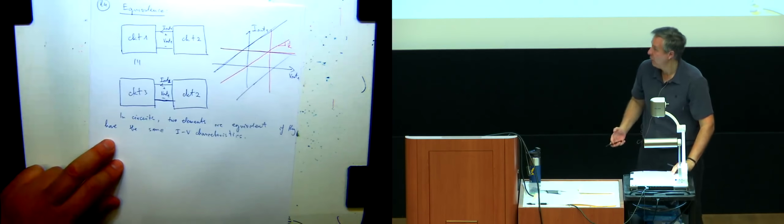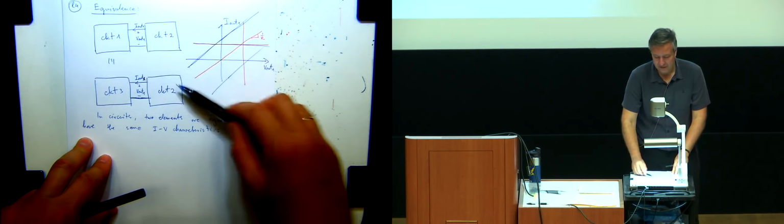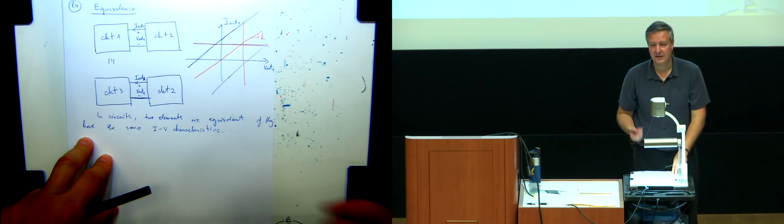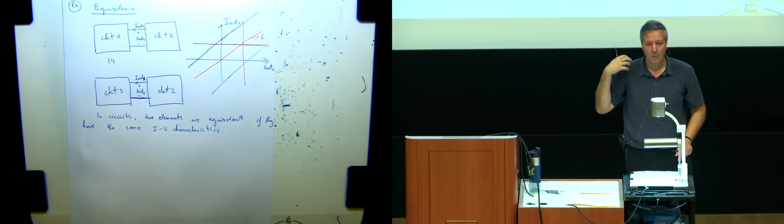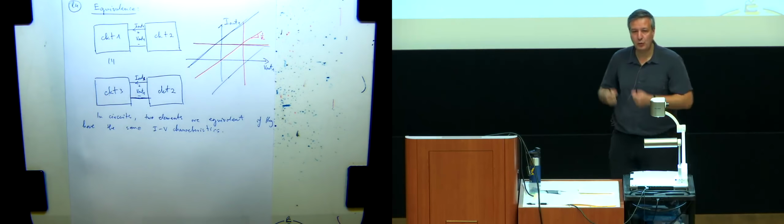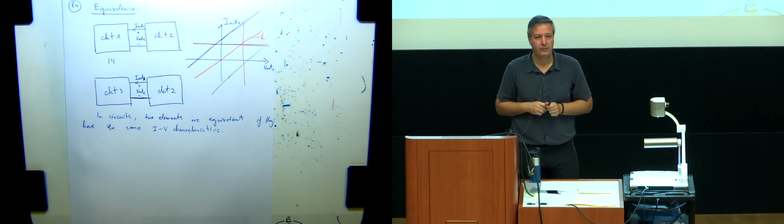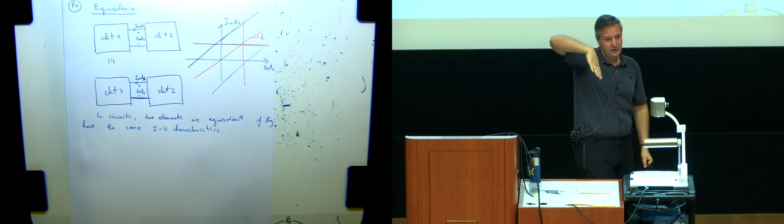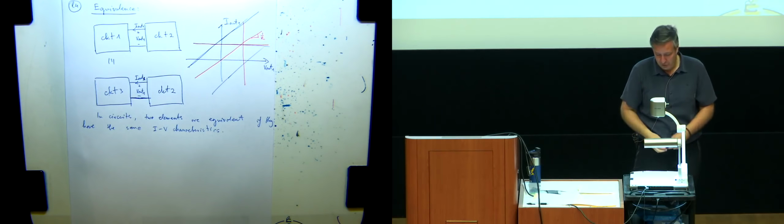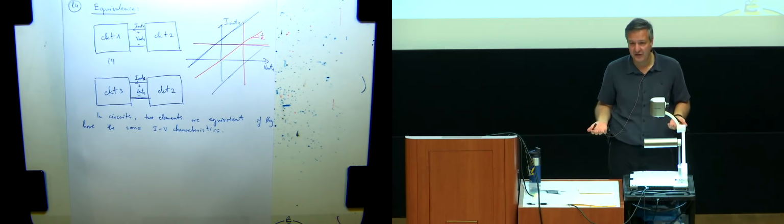Right. And given that we're doing linear circuits, meaning every single one of these curves is a line, right? How many parameters do I need to emulate this line, to be able to represent this line? 2, right? So 2 points will define a line. An offset and a slope would define a line, right? And we just showed here that a source provides offset and a slope is provided by a resistor, right?